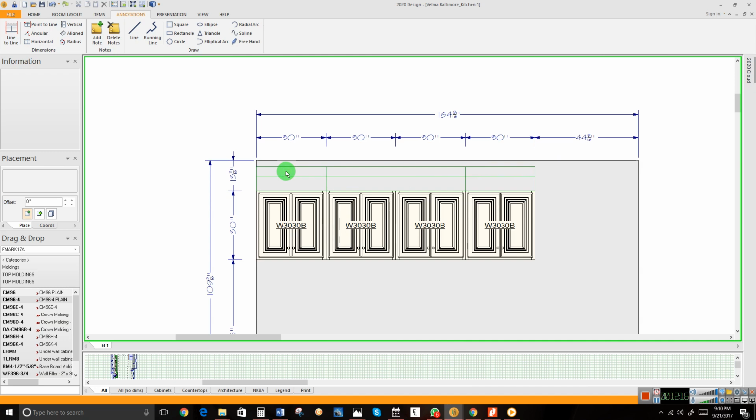Remember, you can right click on this and say up and down. At this point, you can come to this side and change it to 93 and 9/16 from the bottom. It drops it down. You see that? That's one option of moving up and down. Now, check out this one too. If I right click, up and down, but I'm taking it up, it's not coming down.